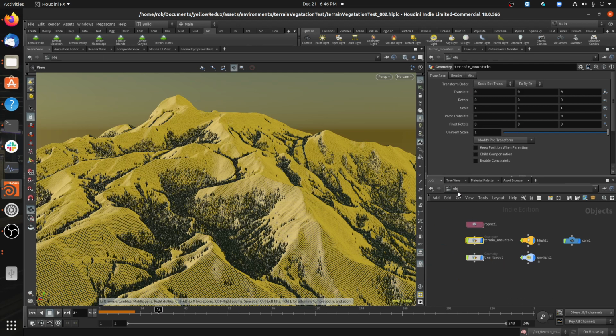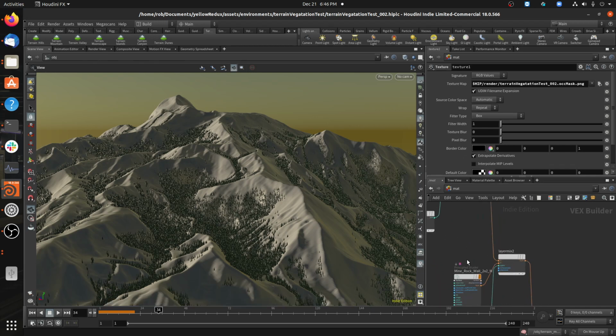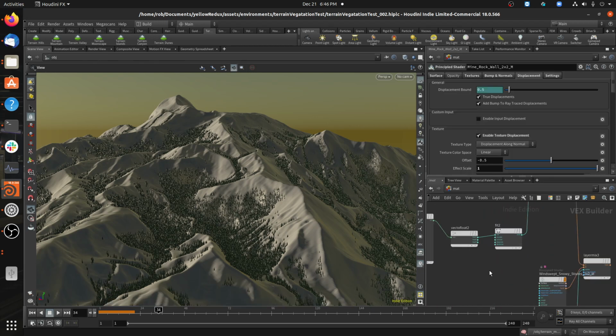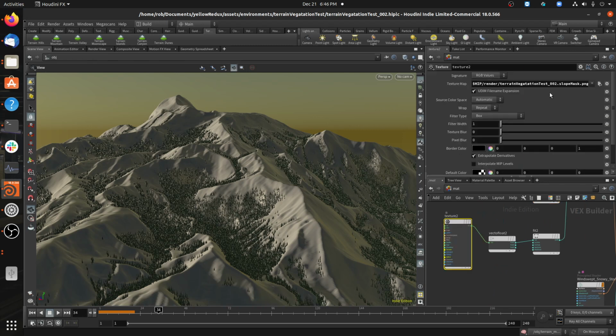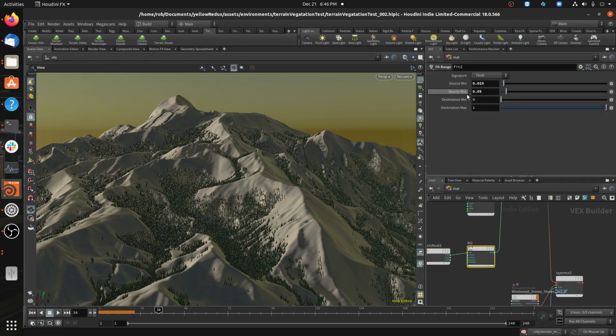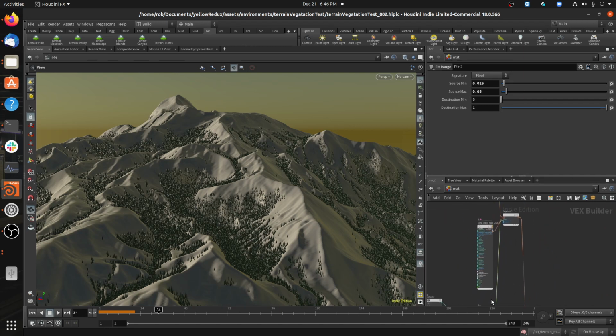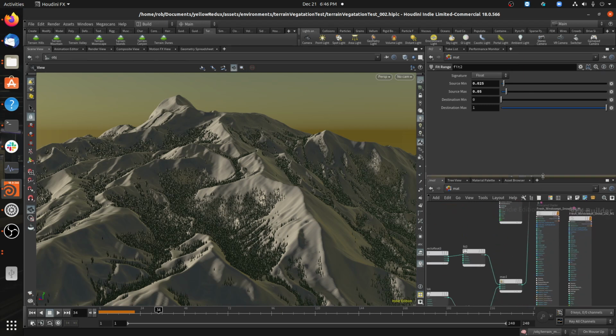So I'm going to go back out to my materials now. We've got our first layer mix, right? And now it's just repeat. We go into alpha, bring in the next one, and bring in another texture map. In this case, the slope, same thing, vector. And then this is using the same lookup. I think some of these have a different lookup, but same. It just goes through that process all the way down to layer mix 3, which is bringing in windswept.